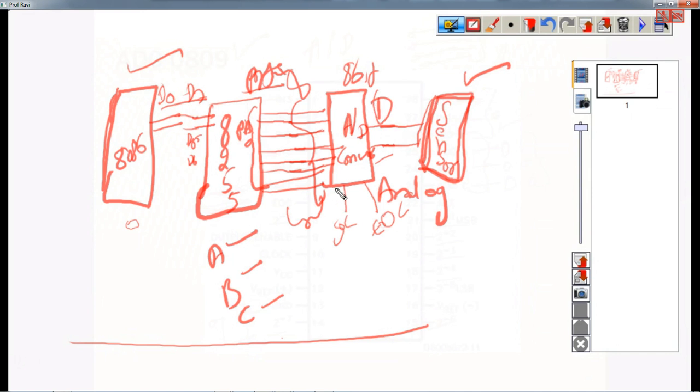So then here you have 3 signals, the channel select lines, for selecting any one of the analog inputs. So we need to deal with 3 plus 1 is 4, plus 8 is 12, plus 2 is 16 pins, 16 signals. We should know about interfacing, it needs to be interfaced to the 8255. So now let us see how it can be done.